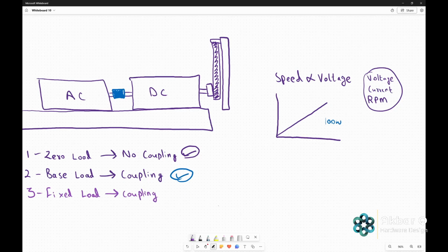This allows us to determine the efficiency of the motor across its different performance levels: at low speed, at medium speed, at high speed, and so on. Because we have the efficiency throughout the motor's curve, we can eliminate that and get the generator efficiency in isolation.